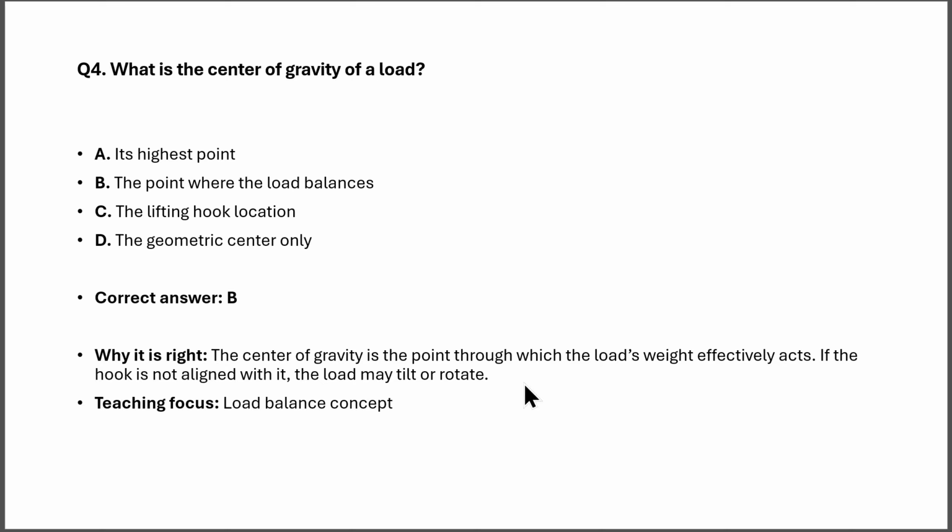The center of gravity is the point through which the load's weight effectively acts. If the hook is not aligned with it, the load may tilt or rotate. Teaching focus. Load balance concept.